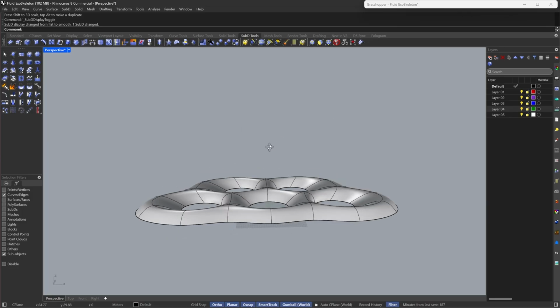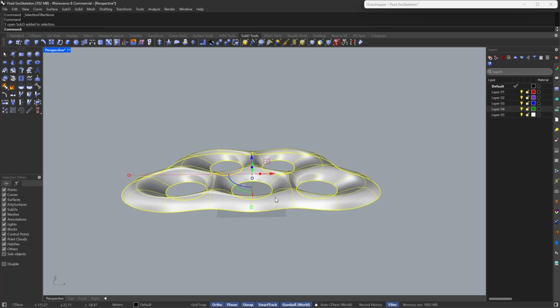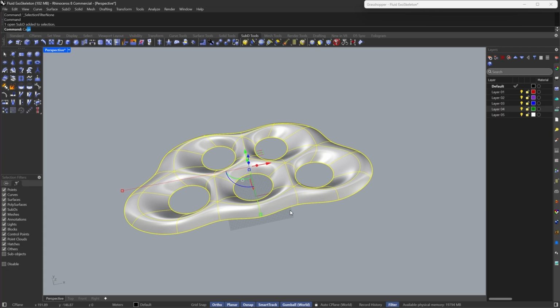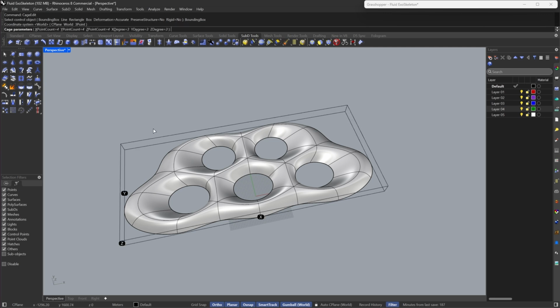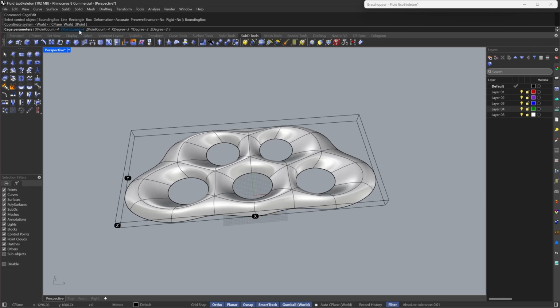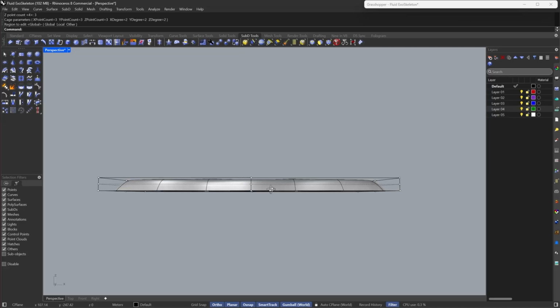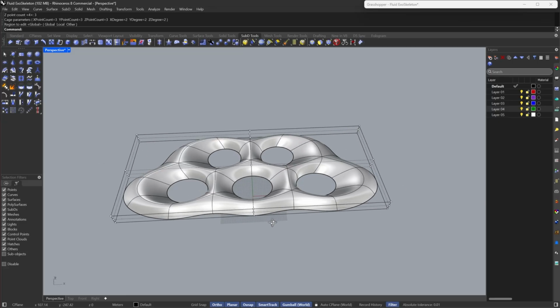And this is good. We can take it a step further and go to cage edit, and right now I need a bounding box, and click OK. And right now the bounding box is 4 points by 4 points by 4, so probably in the X direction I will keep it 3 maybe, and then 3. Actually, let's keep them all 3. Let's see what we are dealing with. And right now you will have your cage something like this, which is kind of good.